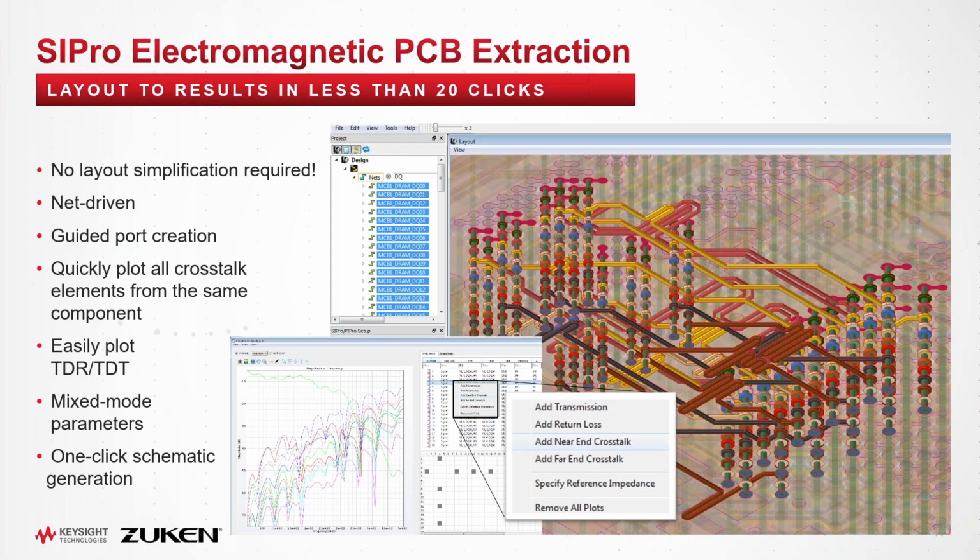So in this case, our solution does not use any transmission line models. What we use is a 3D planar technique called method of moments for the traces. And when it comes to the vias and transitions from via to strip line, that is handled with a finite element method solver. So together you have two pure EM techniques that are combined into one simulation engine. And we get results that are accurate, but in a very practical simulation time.